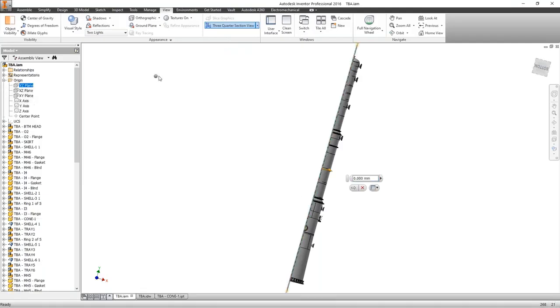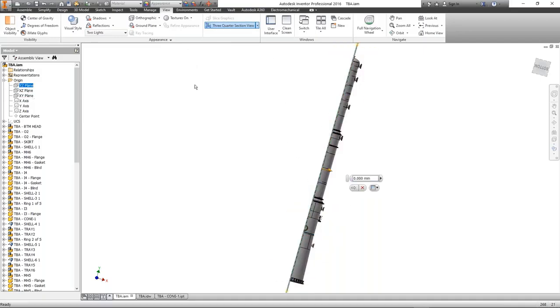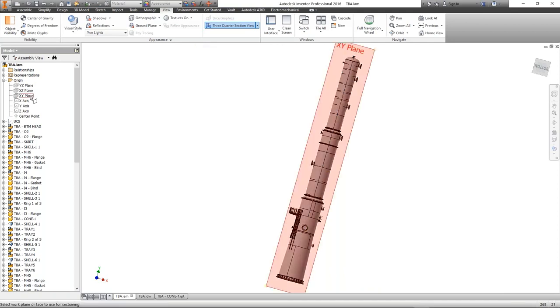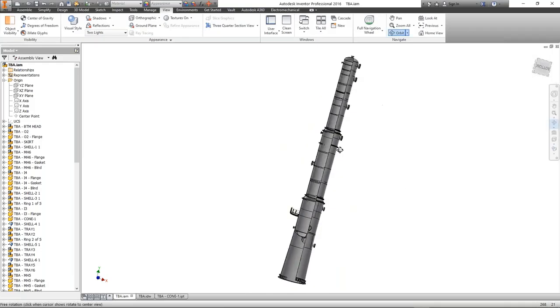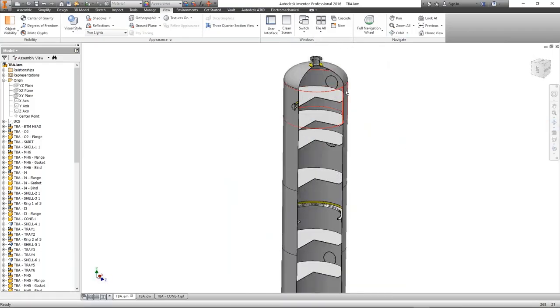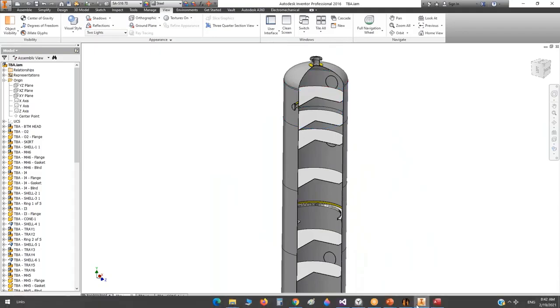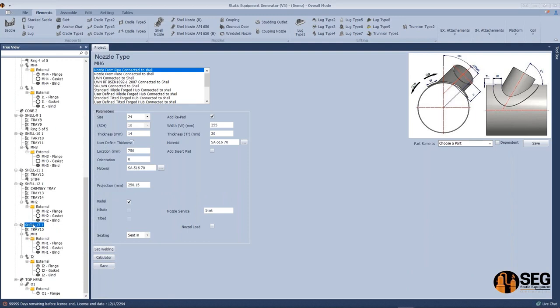Okay, but I'd like to inform you that it's not a detailed demister. It's just for your drawing, not a detailed demister. It's just to indicate that you have a demister on that level in your drawing. I will show you this point here. Regarding the demister, for example, let's add a demister on the last shell course. So let's select the last shell course here, which is that one.